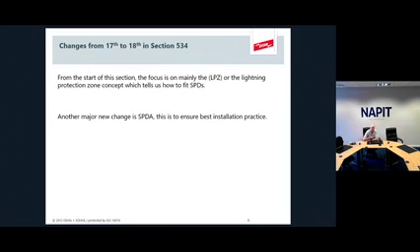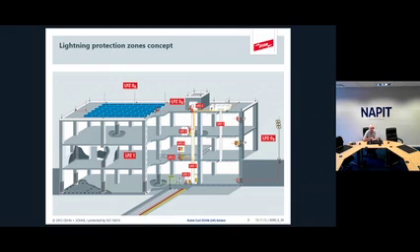So, having had a look at the risk assessment part, we're going to move on to section 534 now. So there are two main new parts. One is the lightning protection zone concept, which tells us how to fit the SPDs. And then we got something called the SPDA, or Surge Protection Device Assembly. And that tells us a lot about the best installation practice. It's about cable lengths and fusing, stuff like that. So the LPZ concept, what you're looking at here is a sort of an overview of the whole thing.